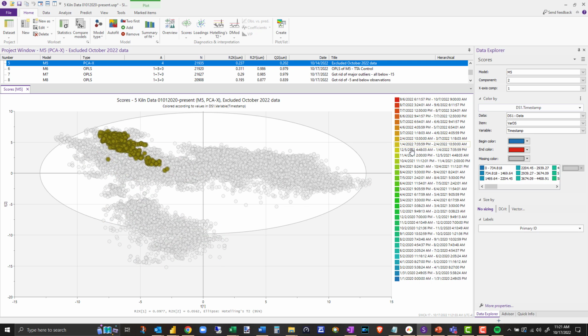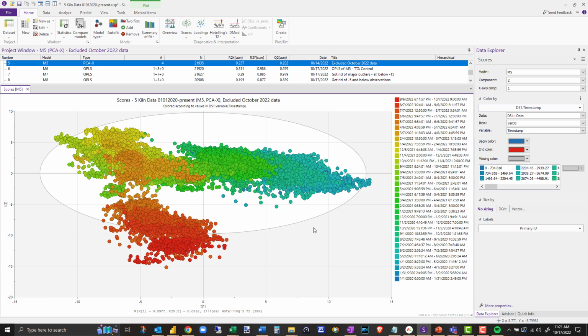They're hunting and changing stuff. Now, there were some things that I ended up finding, like a pressure transducer, and you could tell just by the data it didn't work for a really long time. It was just around zero, and then there was no data for a while, and then all of a sudden it started working, right? Those are the kind of things you have to recognize.